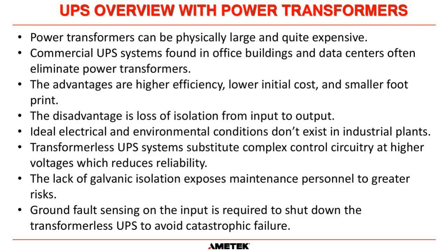But there are disadvantages to that also. Primarily, the loss of isolation, input to output. In industry, it's not an ideal controlled environment, or rarely is. Transformerless UPSs substitute complex circuitry, such as in the battery charger, at higher voltages, and the reliability is just not there, not compared to the traditional UPS.